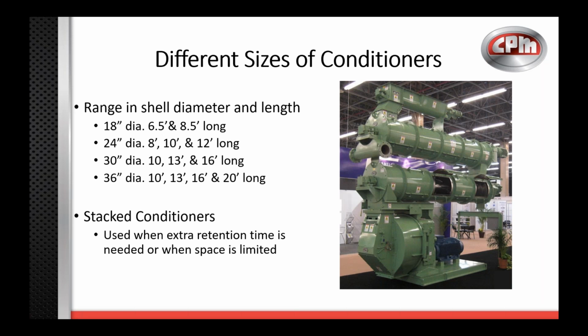Some of the things that we can do with them is we can stack the conditioners. You can see that in the picture there on the right. That shows two of the same size conditioners stacked on top of each other. Some of the reasons we may do that is if you want to double your retention time, if you are running 60 seconds and you want 120 seconds of retention time, we can take two of the same size conditioners and put them on top of each other to achieve that.